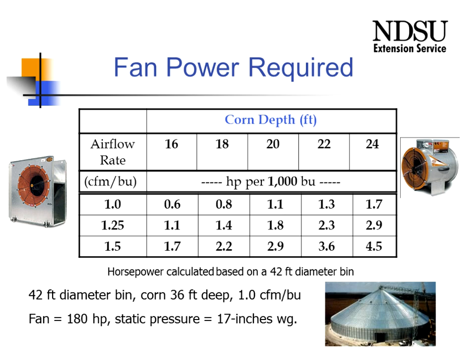The same thing is true as we increase the airflow rate. Going from 1 CFM per bushel up to 1.25 CFM per bushel increases the horsepower requirement from 1.1 to 1.8. And so we're limited to approximately 1 CFM per bushel if we're going to go on a full bin of corn.